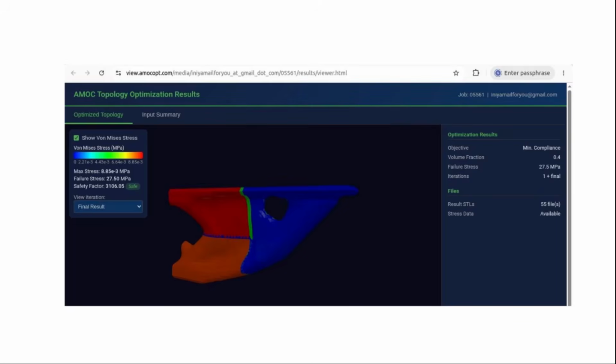So here we have a term called safety factor, which compares the stress this material undergoes to the failure strength, and it gives a value of above 1. Actually this is way higher than 1. So this structure is safe, it can carry a load of 10 kg and the volume fraction of 40% is fine, and the safety factor is much higher than 1.